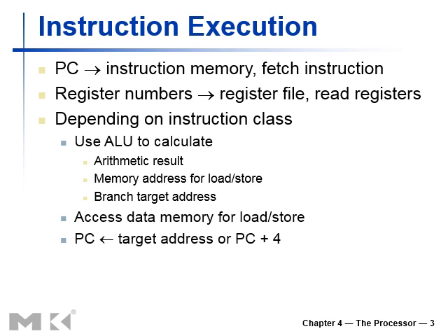While coming to the instruction execution, first of all, we're going to fetch the instruction. That is the important step. And from where we're going to fetch our instruction, definitely we have seen that we have got a dedicated memory source that is responsible to hold our instruction, or machine code basically, for the instruction. So that is known to be the instruction memory. And how we're going to access those instructions, we've got a program counter. Basically, that is a dedicated hardware component that provides the addresses for those instructions.